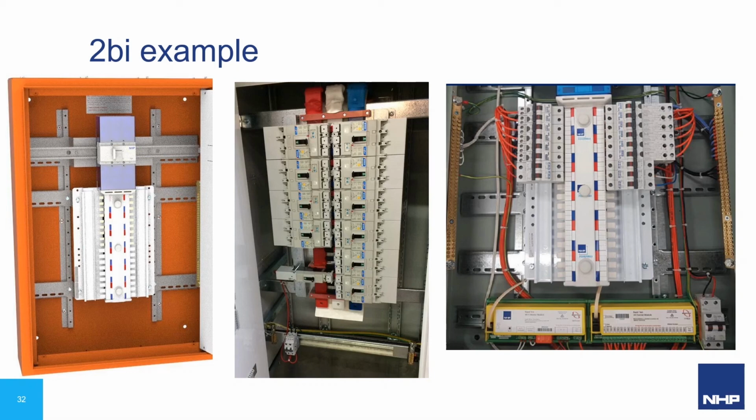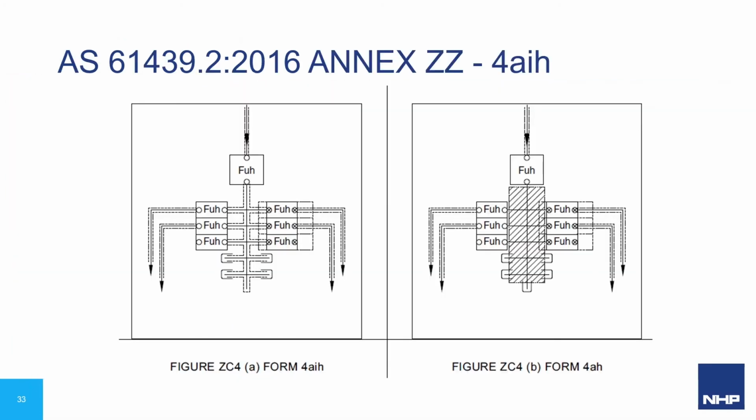There is no strict IP2X requirement for the load side of the functional units or terminals for outgoing conductors, but it is typically achieved in practice. Tee-off caps are required on the bus bar if no MCBs are fitted.